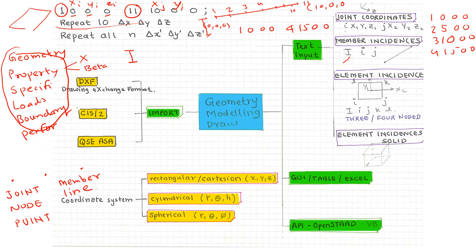So there is an option. If I have nodes in a series, node 1, 2, 3, 4, 5, and I want to put them in a circle. So node ID I have written this way. Let me use another color for member ID. So I am writing members in this color, 1, 2, 3, 4. So I have to create 4 members. By a single line I can do: member 1 is between 1 and 2, and do this up to the last member, which is 4.